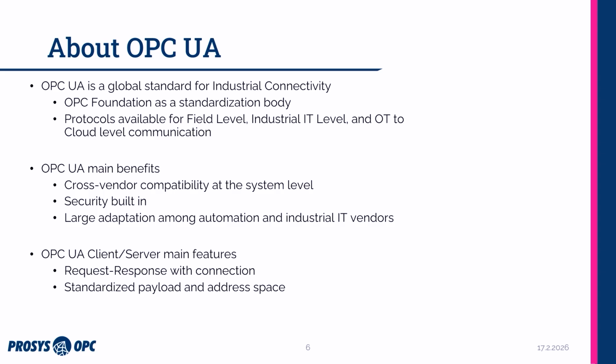The benefits of OPC UA are that there is cross-vendor compatibility due to the standardization. It has security built in and very large adoption in the OT companies. The main protocol within OPC UA is client server, which we recommend everyone to use on the OT level.